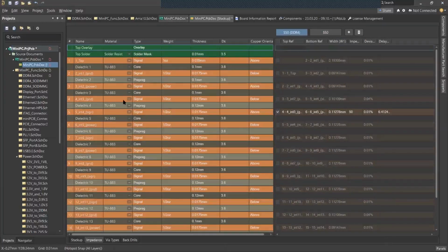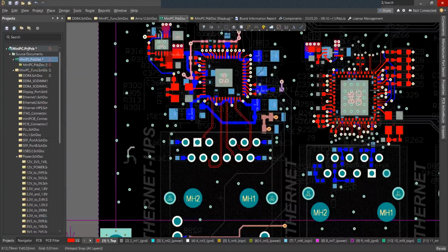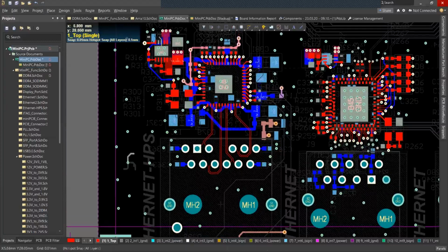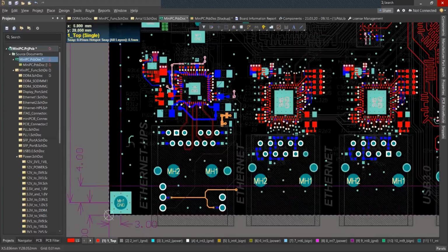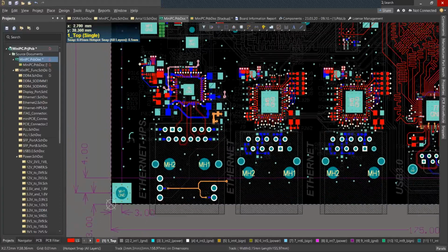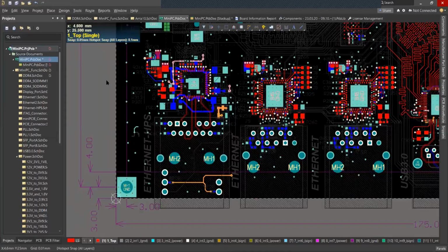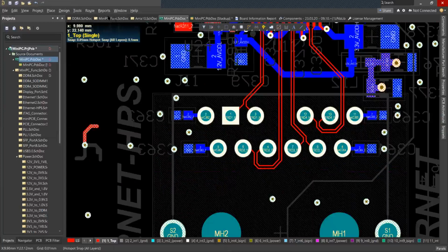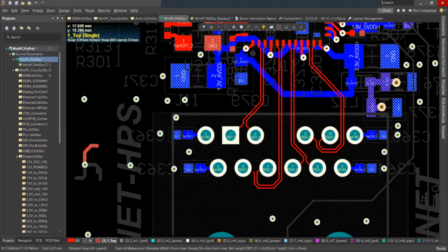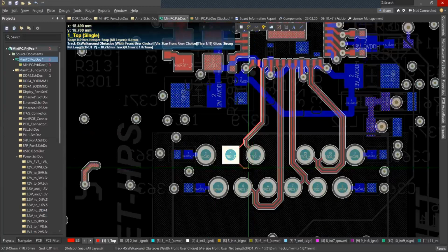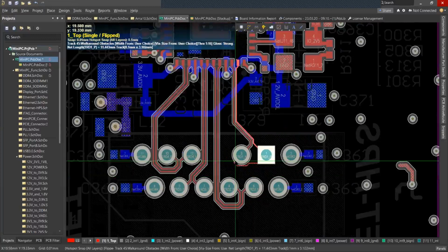So this one is there, and under Altium Designer 20, under Route we can choose interactive routing, and there you can press Control plus F.